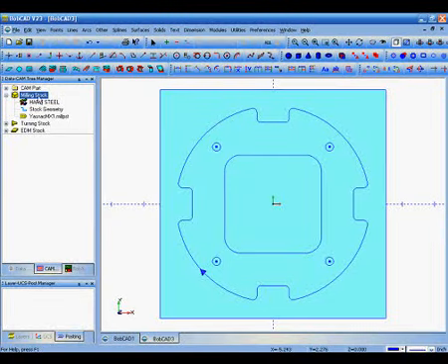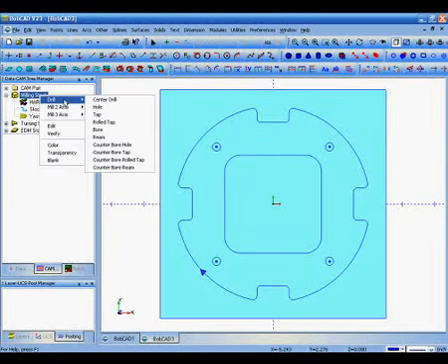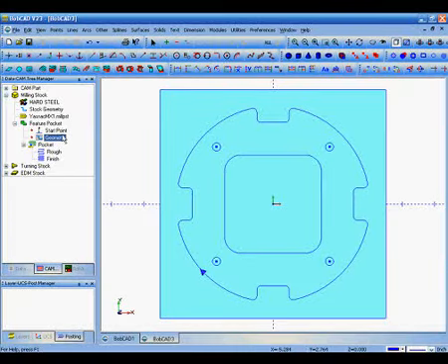To add the toolpath, we're going to right-click milling stock. All of the toolpaths are located in this menu. We have drill, mill 2-axis, and mill 3-axis. In this case, it's a 2-axis cut called pocketing. It loads a feature pocket. Everything below this feature pocket has to do with this pocket: a start point and geometry. It's necessary that you at least select geometry. Start points are optional. In this case, we will not be using a start point.